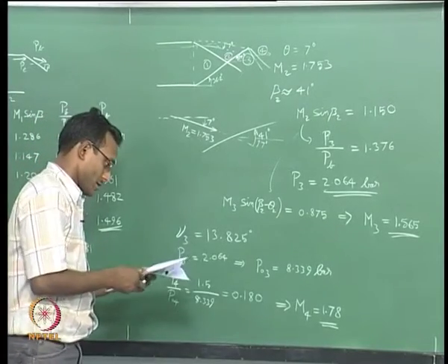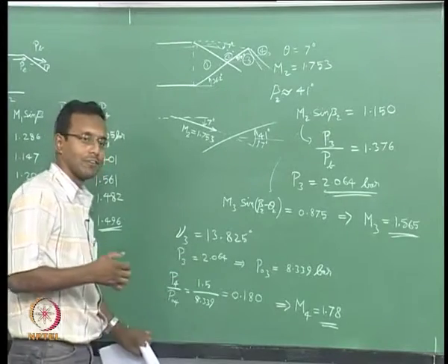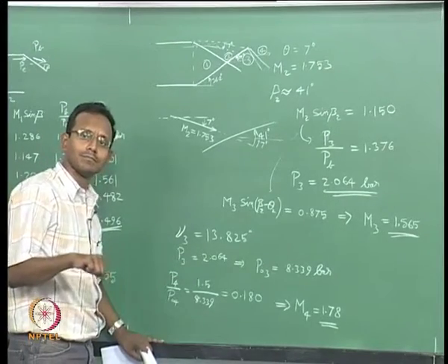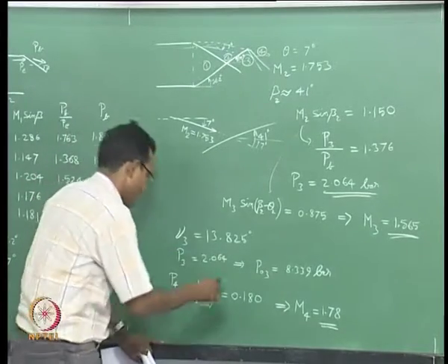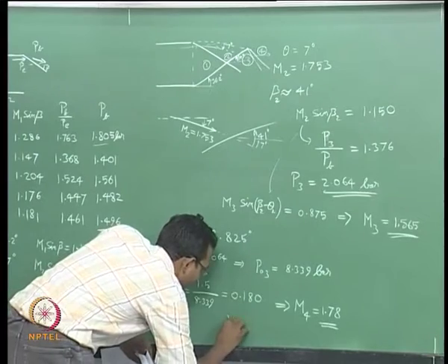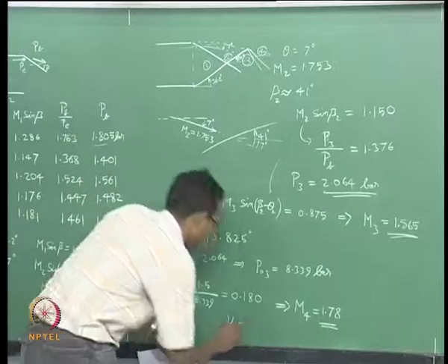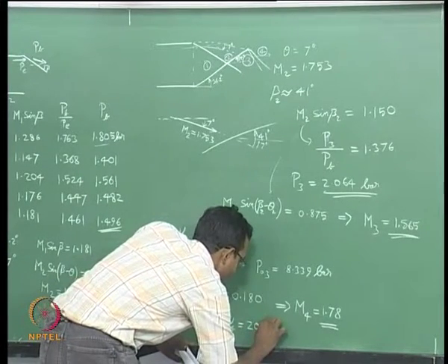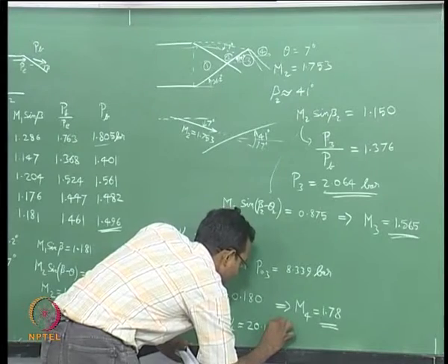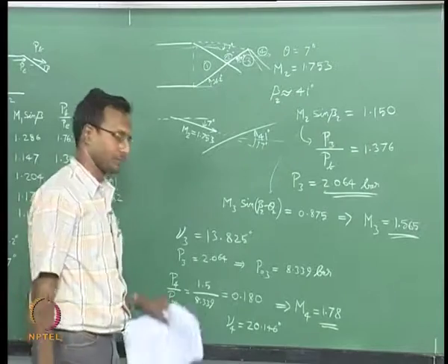Okay. How much did it turn the flow by? How will I find that? Again, I have to find Prandtl-Meyer angle here. So, I will find nu 4 for that Mach number, that happens to be 20.146 degrees. This is the number I have there, 20.146 degrees.